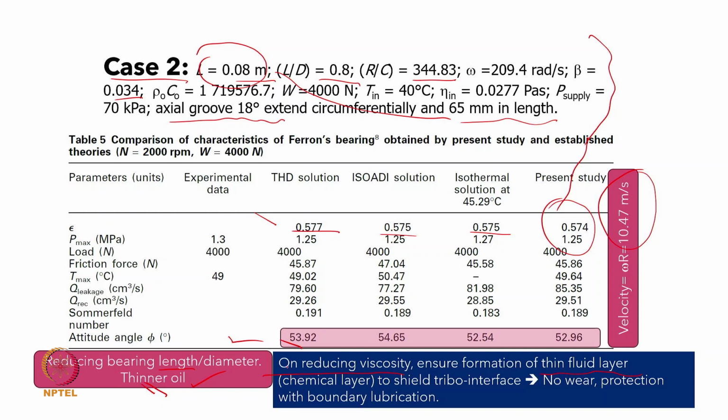It can be physical adsorption, chemical adsorption, which we have studied earlier. It should shield the tribo interface everywhere, and then protection by boundary lubrication is ensured. If it is done, then it makes much more sense.